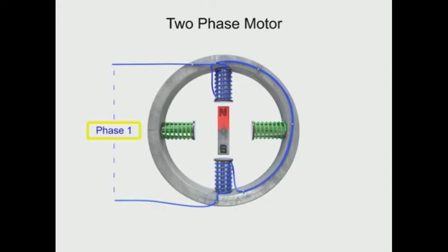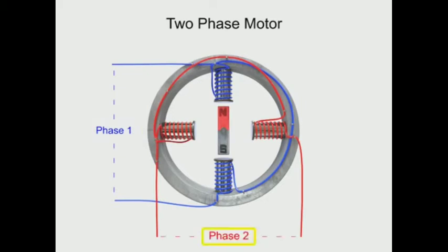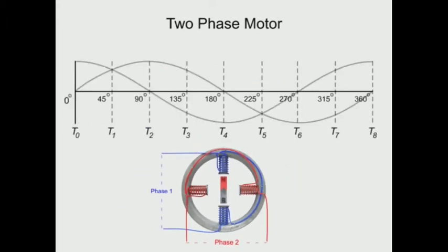Synchronous motor. In a synchronous motor, the AC voltage is applied to the field coils, called the stator in an AC motor. This means the magnetic field is changing in time in phase with the impressed AC voltage. The armature, called the rotor for AC motors, is either a permanent magnet or a DC electromagnet, and possesses a